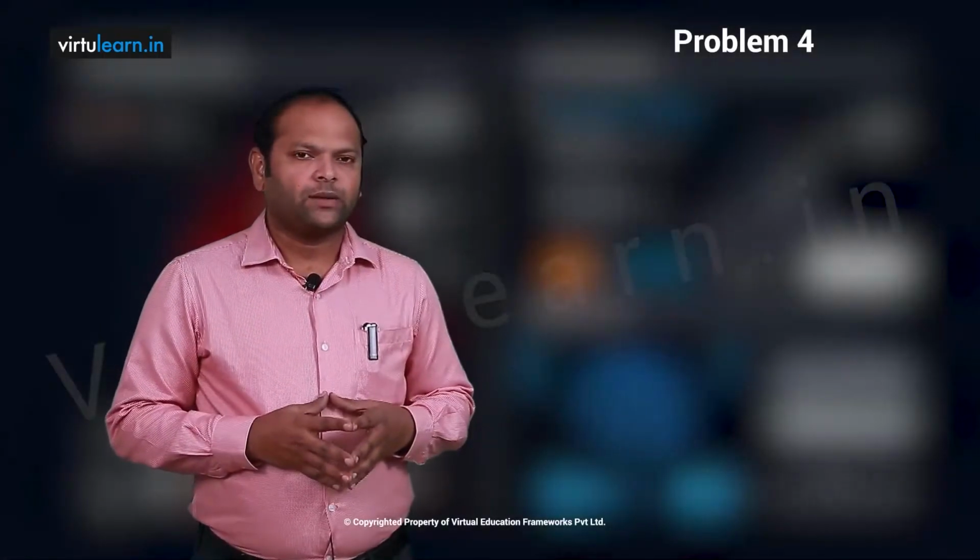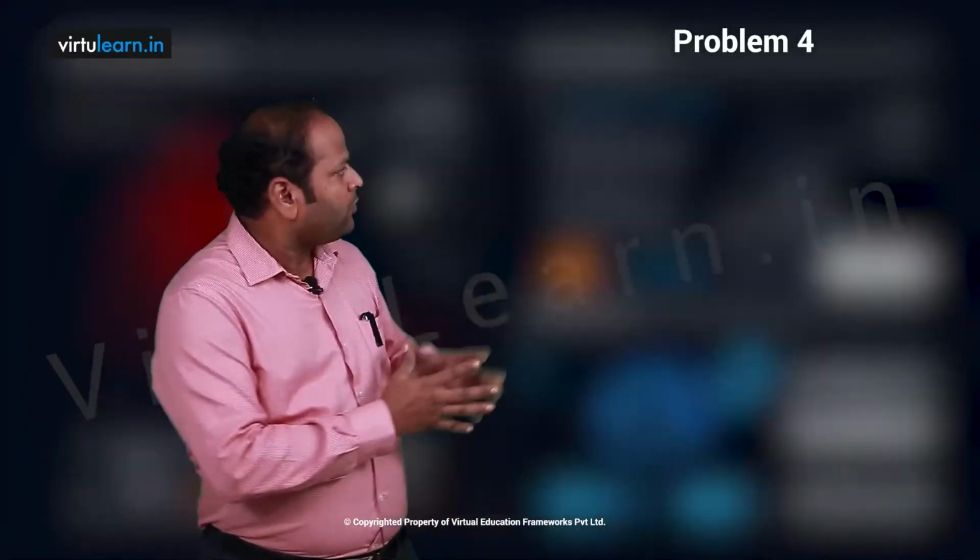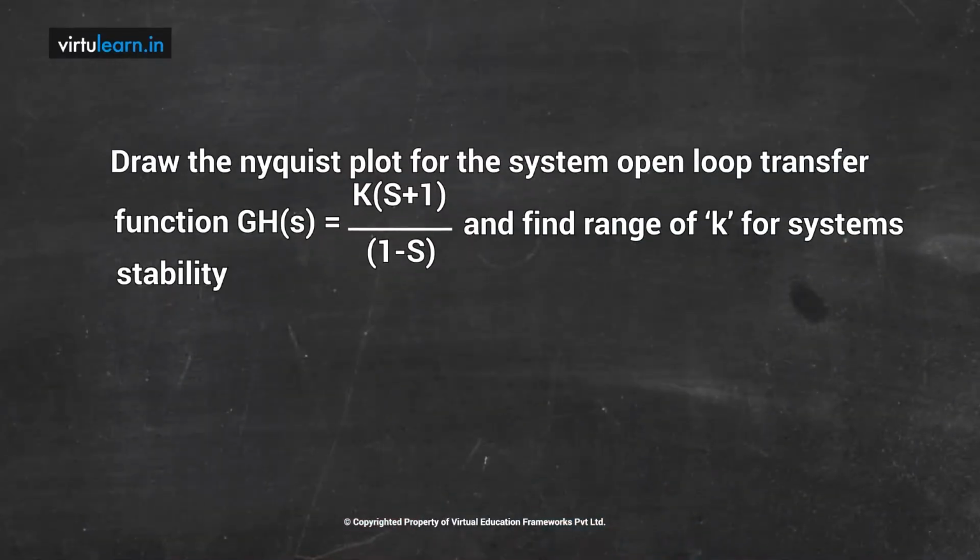Let us look at another problem and see how to plot the Nyquist plot to investigate the closed loop system stability. The problem statement goes like this. Draw the Nyquist plot for a system whose open loop transfer function GH of s is given by K into (s plus 1) divided by (1 minus s). Find the range of K values such that the closed loop system is stable.